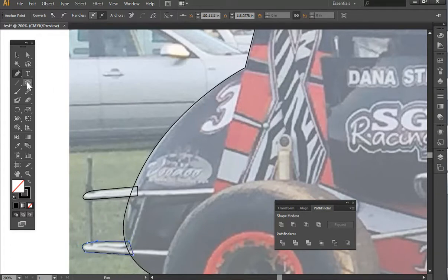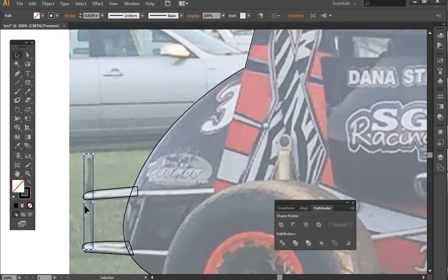Like that. And what I like to do for bars and stuff like that is just use the square tool. It makes a nice uniform look, and we can draw a bounding box around all of the artwork. When you draw a bounding box around it, you just click and drag, and whatever you drag over top is going to get highlighted in blue here. Go to the Unite button, click that, and there you go. It's part of the outline now.